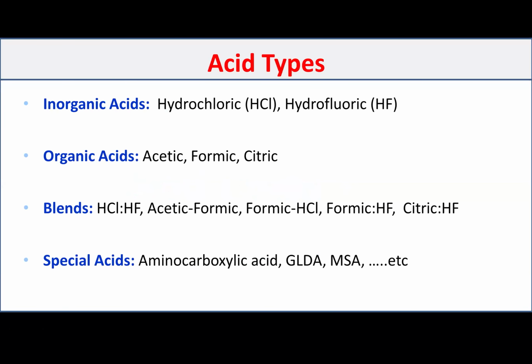For acidizing, we have different acids that we typically use for matrix acidizing. Let me start with the first one, the organic scale, organic acids. Typically we have two main acid systems. Hydrochloric acid, which is HCl, is the main acid for matrix acidizing, the most used acid. We will discuss each one of them in the upcoming slides.